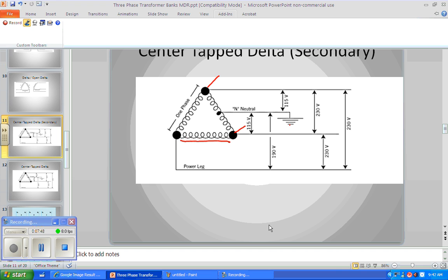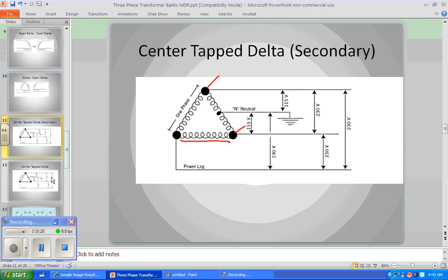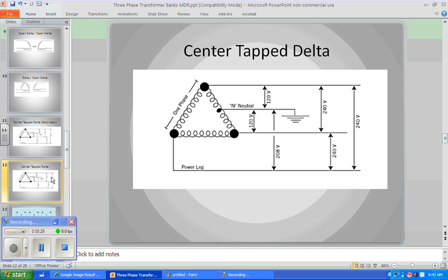Okay, so it becomes very important to be able to figure out which winding is that secondary winding because, when we make our transformer bank up, if we know we're going to do this ahead of time, it might be a good idea to have a larger one. What happens, generally speaking, is it gets done after the fact, and probably the transformer wasn't being loaded to its maximum load, or nowhere near there, and so it's okay to add a little load to one of the transformers, as long as it's well within its capacity. So we don't want to overload one of the banks or one of the parts of the bank, but we can create single-phase power out of that.